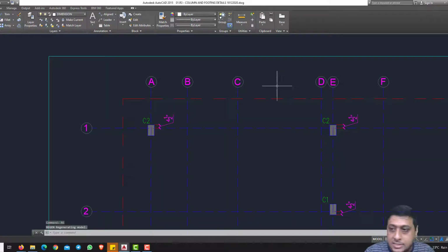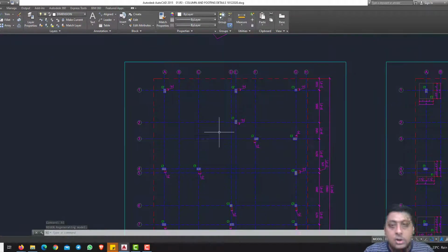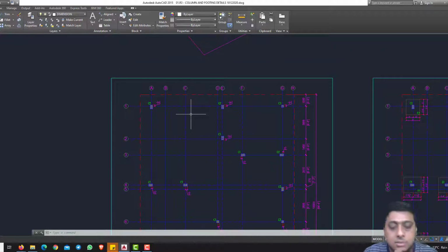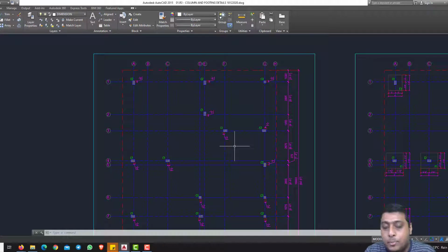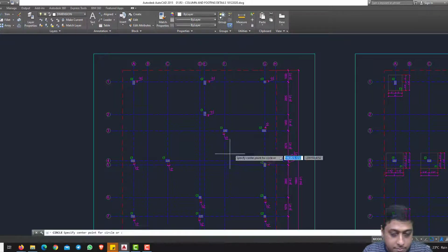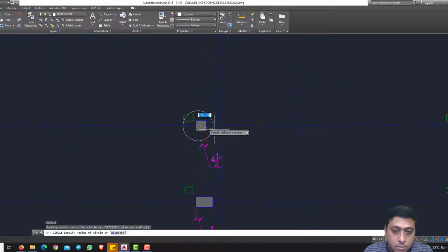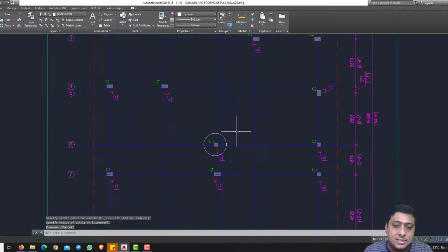Okay. Next, when you are going to the site, you have to see the grid lines. They have given A, B, C, D, E, F, G, H, and 1, 2, 3, 4. Why are the grids very important? Because, for example, if you are having any problem in setting up a column or a foundation, you cannot tell them "in this line or in this part, northeast, north, south." You cannot tell it that way. If you represent it with respect to the grid line, for example, if I am having a problem in setting up this column due to some site conditions,